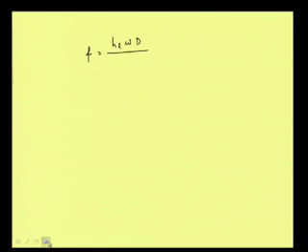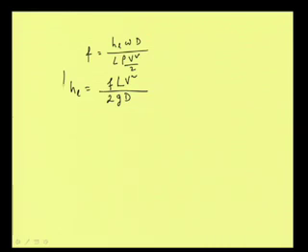So, from here we can write HL is equal to f L v square, with capital L here, then w by rho is nothing but g. So, we can write HL is equal to f L v square by 2 g D, and that is the very popular expression commonly used in pipe flow.